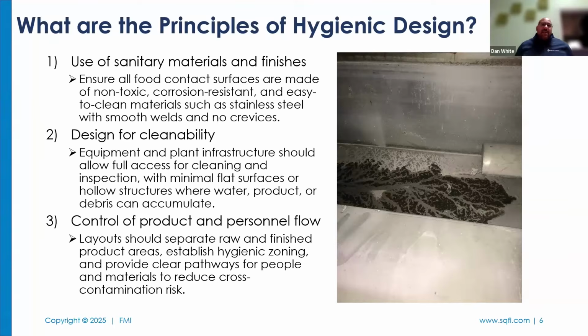Going to the sanitary material, the design for cleanability. I mean, this is a photograph, and it is absolutely a hygienically designed piece of equipment. It started off from the factory in a way that it was always going to be clean. It's a wash down. However, when this vessel was installed by the company that put it in, they didn't appropriately slope the concrete that it's embedded in. And so this piece of equipment is stuck like this forever, essentially.